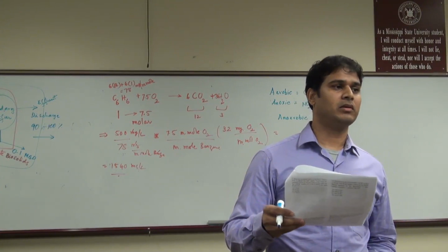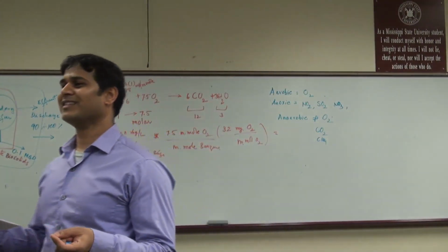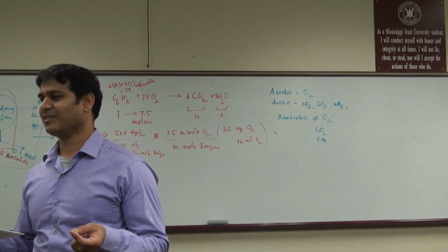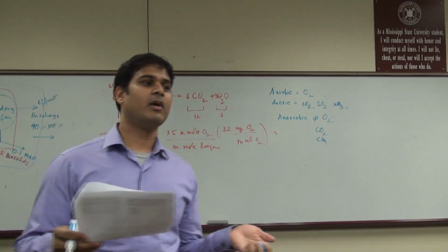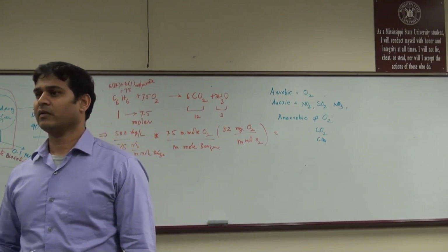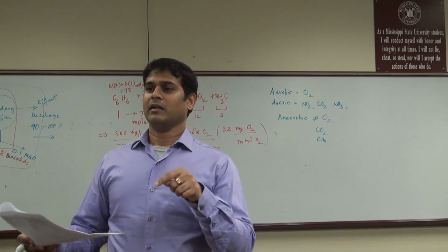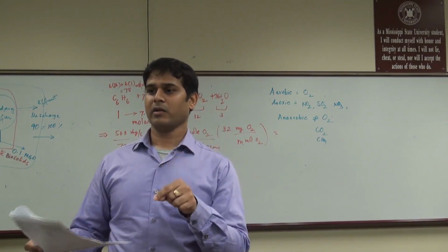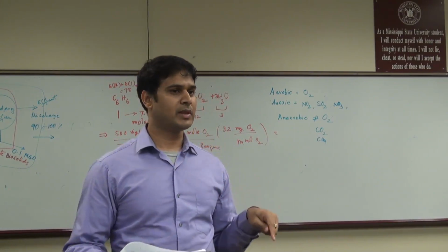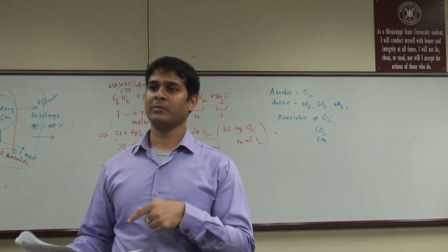Or log removal? I make this joke a little bit sometimes. So what's this? Log inactivation or log removal. Somebody says, oh, we have 3 for log removals. What does it mean? Is that 99%? Is that by 1 or 10? Like 3 log removal means 99.9%. All right, 4 log removal means 99.99%.